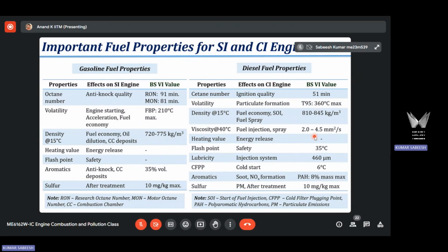So I was thinking of the same only. In addition to reducing this timing, if we make this piston head change, so if we are adding both together, that will help. Yes, definitely. Both can be optimized. We often use the word optimization, right? You need to optimize both based on the timing of injection and the bore. In fact, the bore will play a role. If you have a small bore engine, the wall wetting is generally severe.